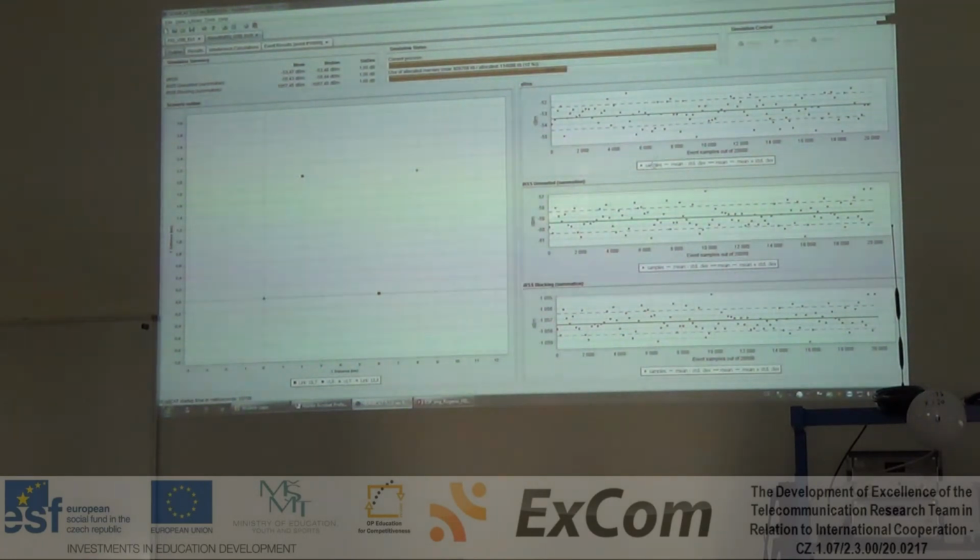Here you can see some statistics of the signals in dBm. Here we have the desired signal, DRSS. And here SEAMCAT divided the interfering signal into different signals. One is the unwanted and one the blocking. I will not enter into details, but we will use only the unwanted, which is more or less on the same level as this one here, about minus 58, 54 dBm.